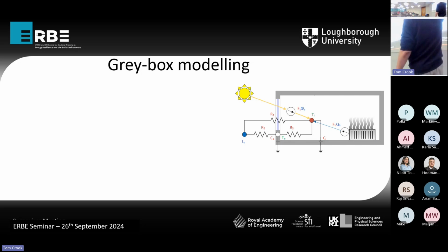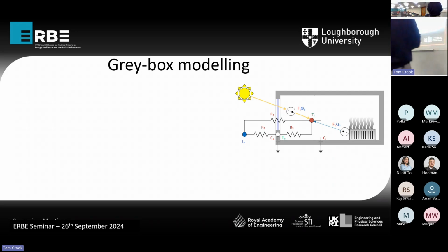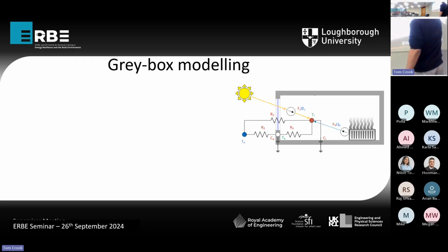We call it CI. And then, as just an illustrative example, we can assume that all the building structure, building envelope, floor, wall, ceiling, are all lumped in another node with a temperature TE. And of course, the building envelope has a capacity for storing thermal energy. So we also have some CE for the thermal storage of the building. Then we have solar radiation, indoor heat gain, and outdoor temperature. And you can see the indoor node and outdoor node are connected with some thermal resistances, which is very easy to understand and imagine.